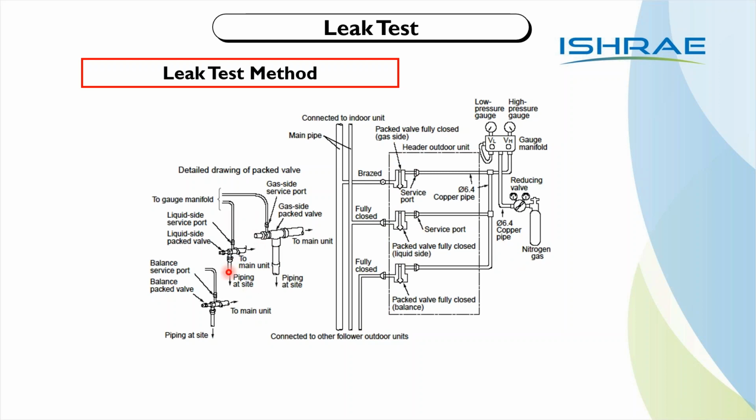Now, this service valve here, you will generally have a gland, and when you open and close the stem, or when you open and close the service valve of the VRF system, make sure that there is no leak in these glands. Generally, we don't check leak here. Now, this is a gray area, and this leak is very, very common because the outdoor unit, you do not know how many months back it would have got manufactured, it would have got stored. The neoprene material inside would have lost its property. So if all that has happened, then there could be a leak here.